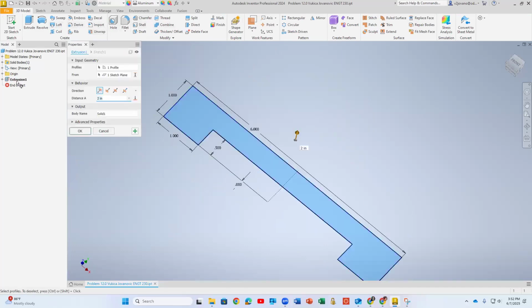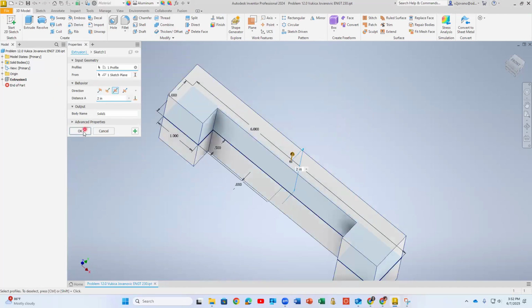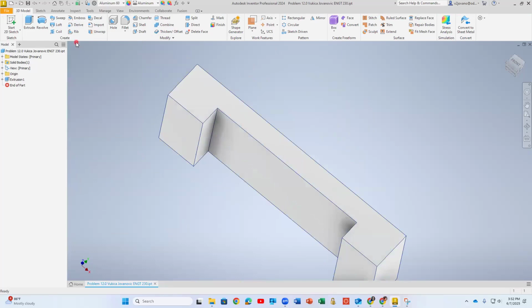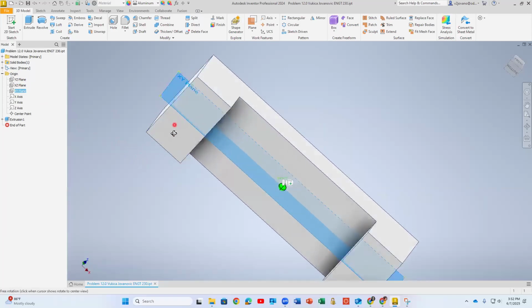okay, so first extrusion, I will just switch to symmetric. So you see, I'm editing the feature, switching to symmetric, and maybe checking what will happen if I add a rib. You see, this command needs a visible, unadaptive sketch. Change visibility of the sketch if you want to use it. Okay, so we need to go to that plane inside. Let me see, which one is it? Not this one, this one. Yeah, you see, it's in the middle.